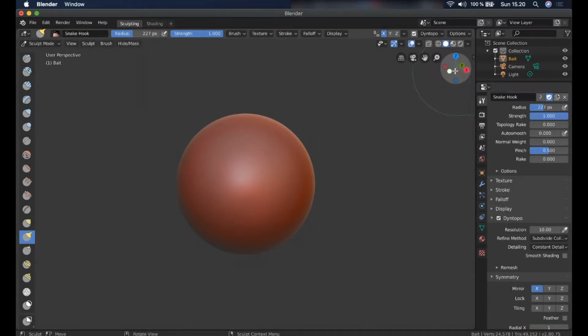So here you can see the orientation, this is the X-axis, but it's better just to grab and pull somewhere and you see how it is mirrored. So I will undo that, but now I have a very good guess how it is mirroring. Command Z for undo on Mac. If you have some other platform, probably it is Ctrl Z.